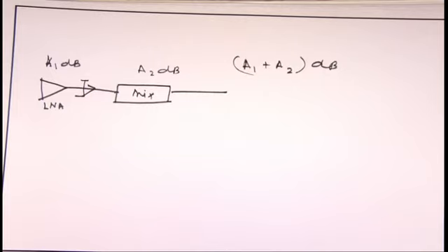But when the LNA and the mixer are inside the chip, then all the parasitics are within your known region, within your control, because you know what is the CGS, because all the models are available in the silicon itself, right.